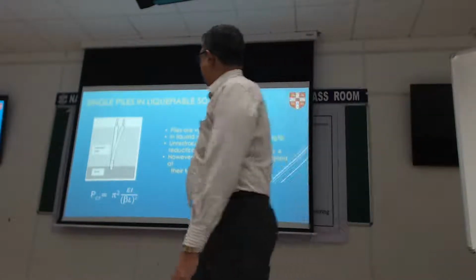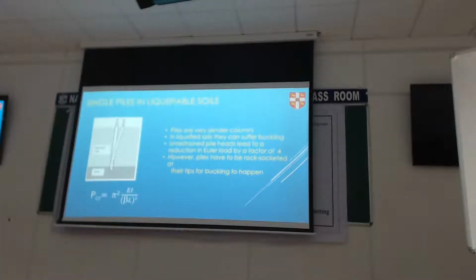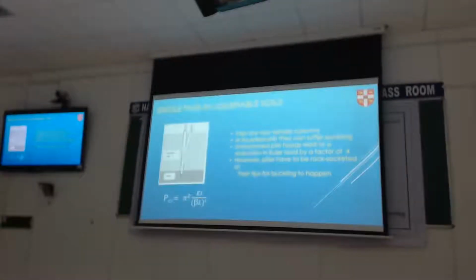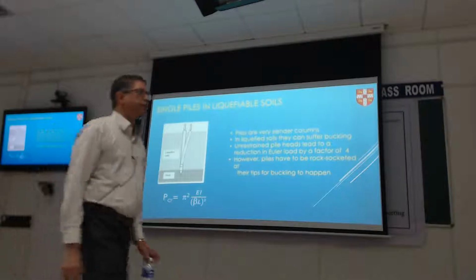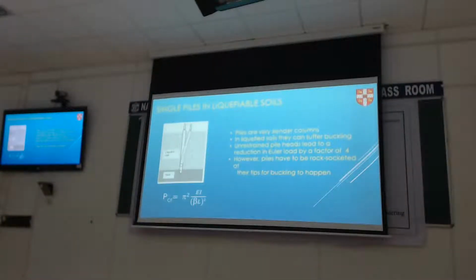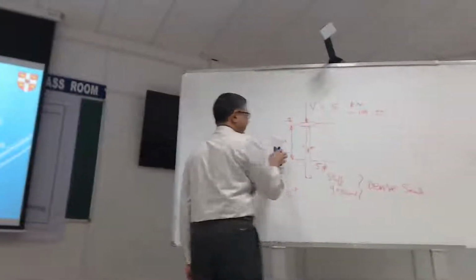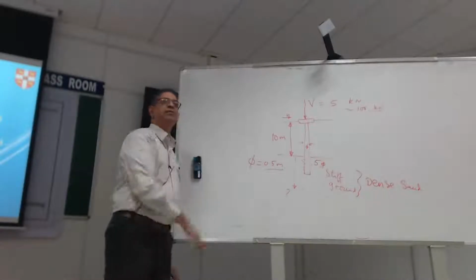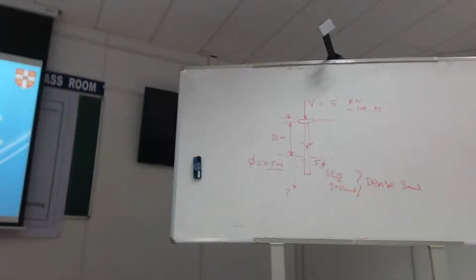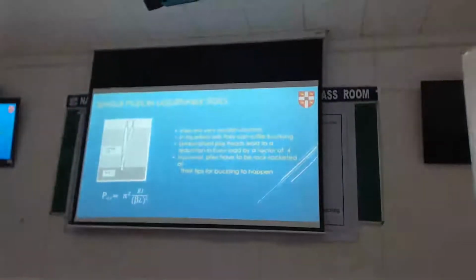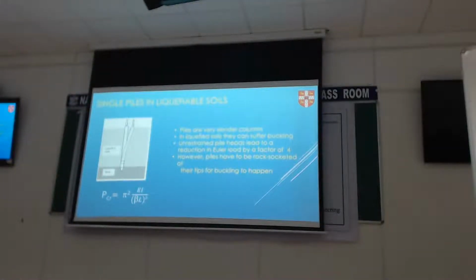Now, if you imagine for a second that we're all structural engineers and we are going to remove this and have that only, then we can solve this in no time at all. Because all you need is Euler's buckling equation and say, right, my unsupported length is maybe 10 meters. Let's work with 10 for now. That will give me L, and beta will tell you the fixity condition.